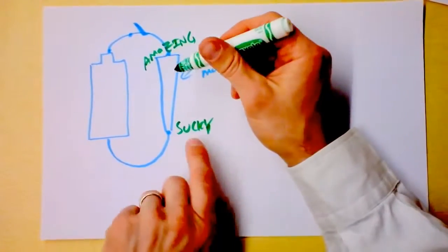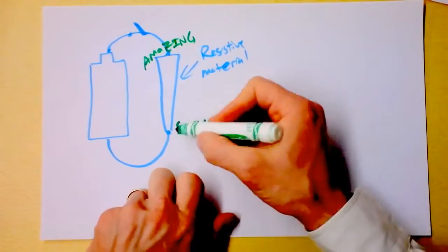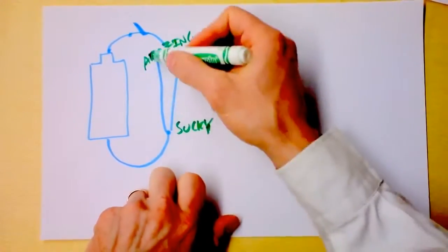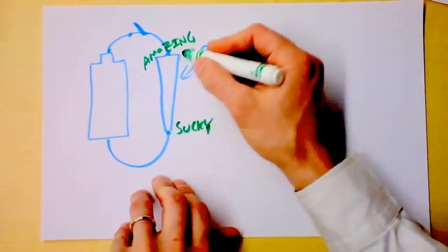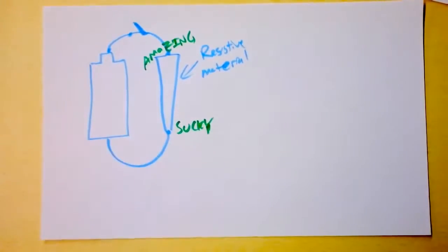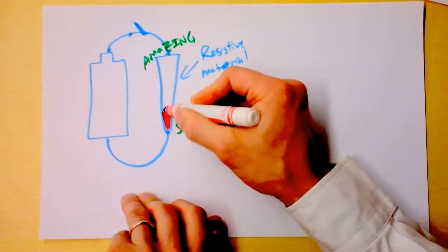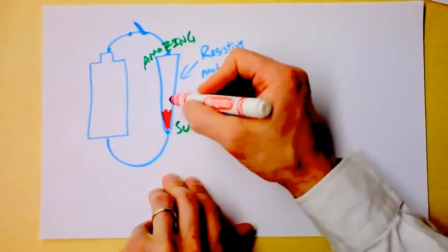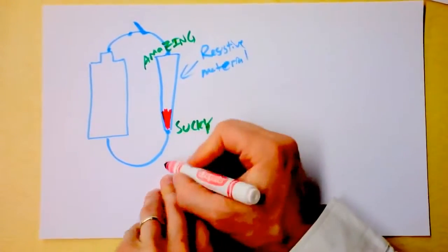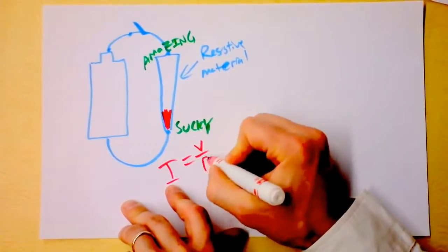So the cool thing is it will heat up more quickly where the resistance is more. And you want to tell me if the strip is shaped like a wedge there, where would it heat up the fastest? Where is the greatest resistance in here? Sure, it's down here. So they're going to give you down here heating up really quickly. Even with a bad battery, down here will heat up, and you'll see red or yellow or however they design it. And then if the battery's even better, then there'll be even more current flowing through here. I guess the current flowing through there is related, let's see, we got V is IR, so I is V over R.